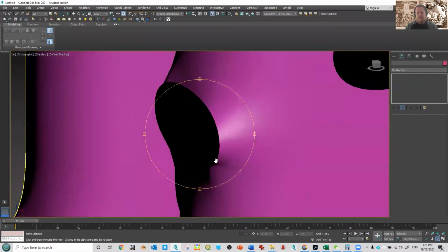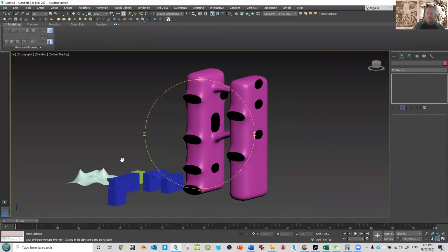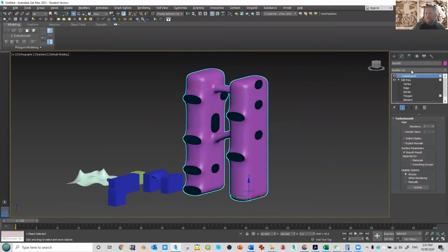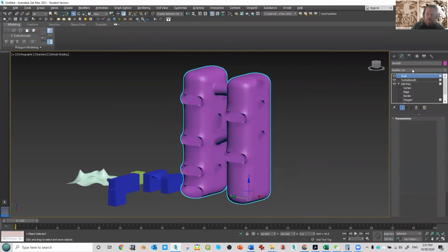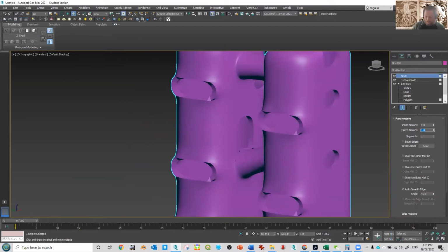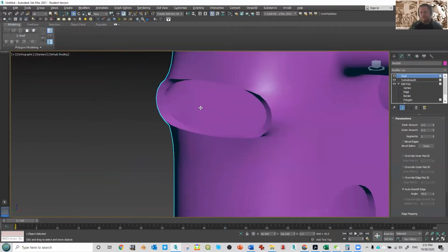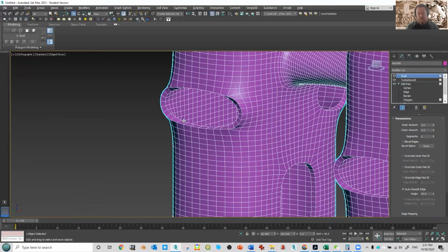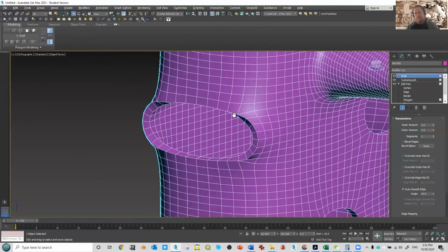If I wanted to give that some thickness, like turn that into, say, a bit of a facade or a shell, what you can do is there's a really nice plugin called Shell, and Shell will let you thicken a surface basically to make it into a solid. So without the shell, with the shell.